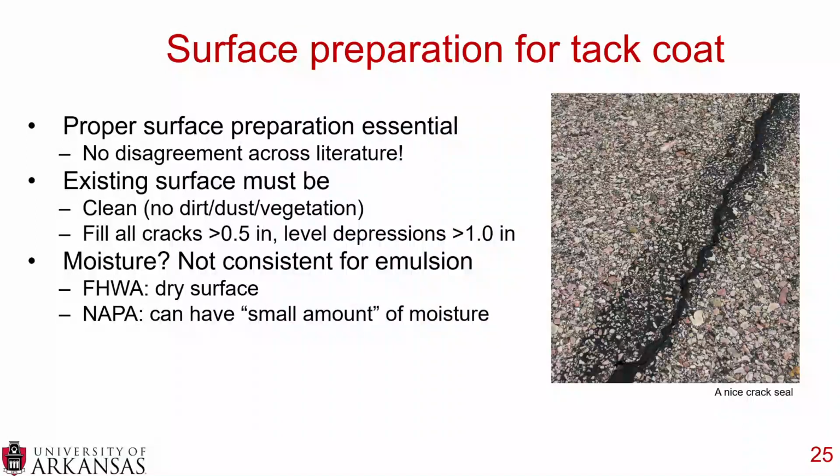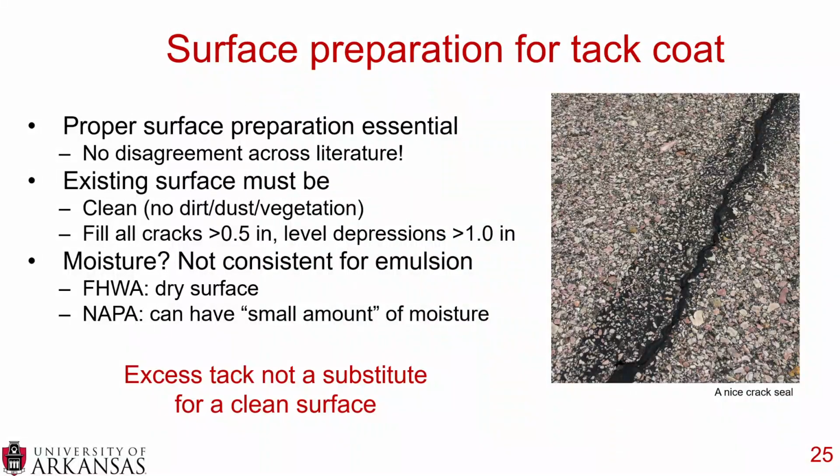If you can define small amount for me, I would appreciate it. I would assume standing water is not a small amount, because a lot of states prohibit tack coat application on standing water. I would agree with that 100%. But can it rain? Is it damp? Is it just spotty? I don't know what small amount is, but NAPA says you can have it.